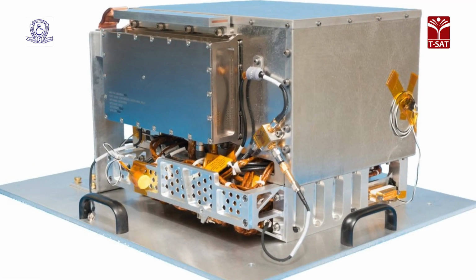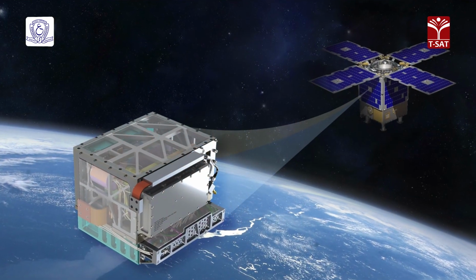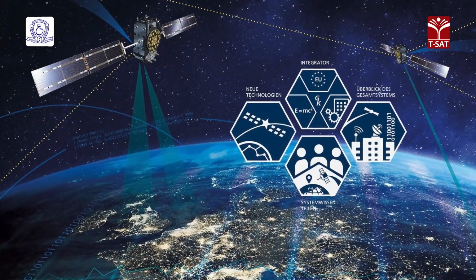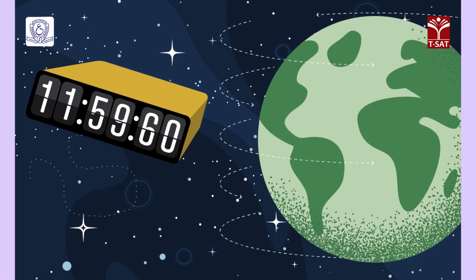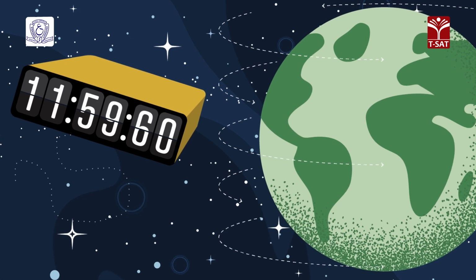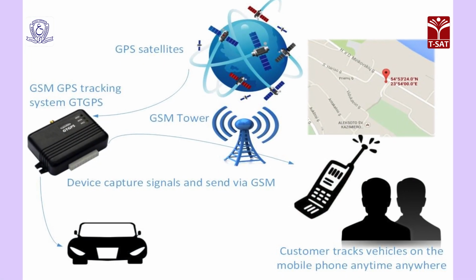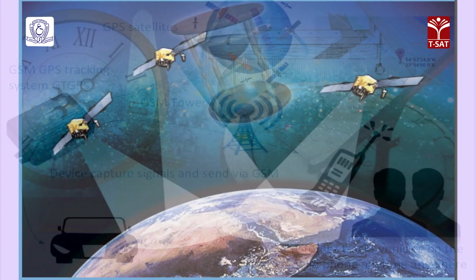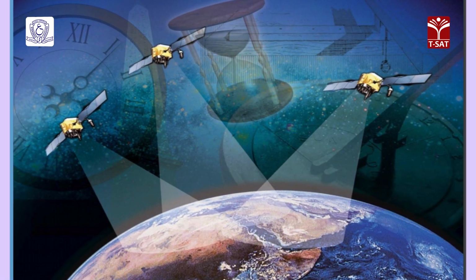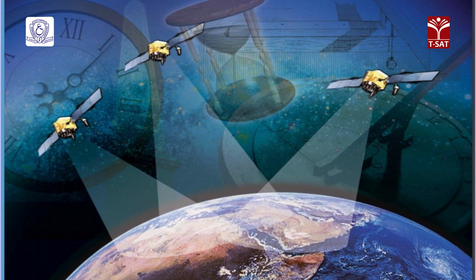Satellite clock errors. The satellites contain atomic clocks that control all onboard timing operations, including broadcast signal generation. Although these clocks are highly stable, the clock correction fields in the navigation data message are sized such that the deviation between the SV time and the GPS time may be as large as 1 millisecond. An offset of 1 millisecond translates to a 300 km pseudo range error. Errors were observed to be statistically independent from satellite to satellite, with significant correlation over time.